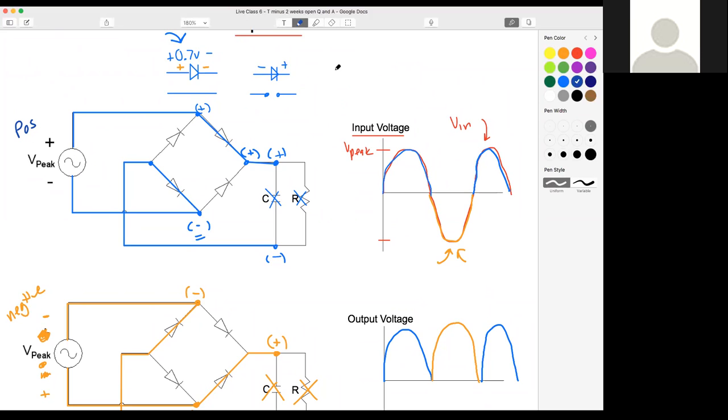So regardless, if we had plus V minus, something that looked like this as an input on a circuit, it would oscillate in a sine wave from positive to 0 to negative to 0. Our x-axis here is actually our time, and the time it takes to complete one cycle would be one complete period, dependent on our frequency.